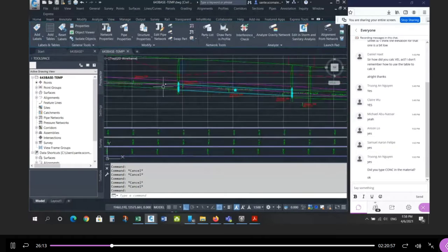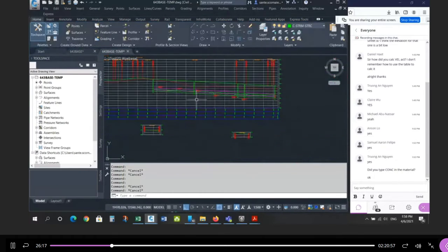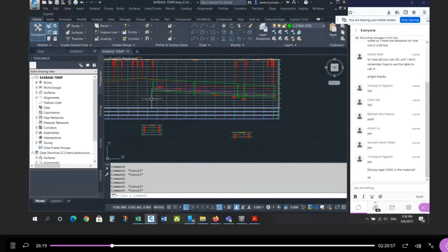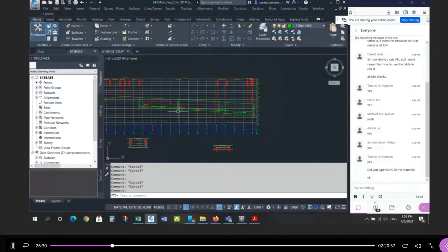And the next pipe, I left it alone. It's still a 450 at 0.5%, and this is still a 375 at 0.5%. But again, I did minimum drop, minimum slope all the way along. Okay? So if we go back to the original, I'm just going to flip between two files. Don't do this. Revise one file only. I just did this so that I could show you the end result quicker.